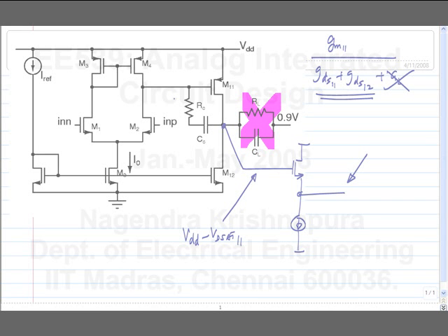So, the function of the second stage in a two-stage op-amp is not to give you DC gain. Okay. What would you do? I have this op-amp and I have a gain of 500. I want to make it maybe 5,000 or maybe even higher, like 10,000. How will I do that? If I want to increase only the DC gain, right? I have not changed the load conditions, I have not changed the capacitance. So, my second pole and all those things have not changed, right? So, I don't have to change the second stage. I need to get just enough gain in the second stage so that the first stage operates without having to drive a large swing. That's all. Okay, gain of 10 is quite adequate, usually.